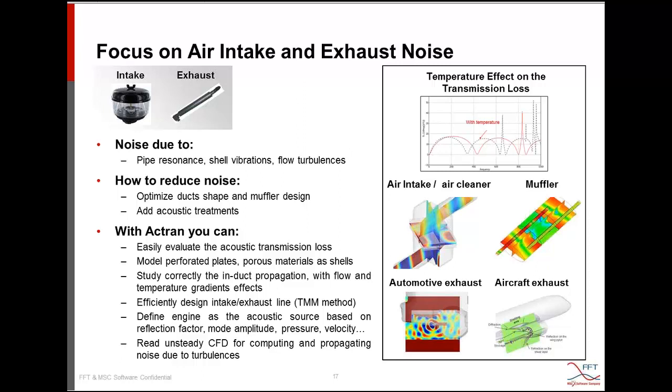On the other hand, the TMM method implemented in Actran, TMM standing for Transfer Matrix Method, can be used to split an exhaust line into several parts, each of them being computed separately, which allows modifying the design of only one part and then recombining the results very quickly.